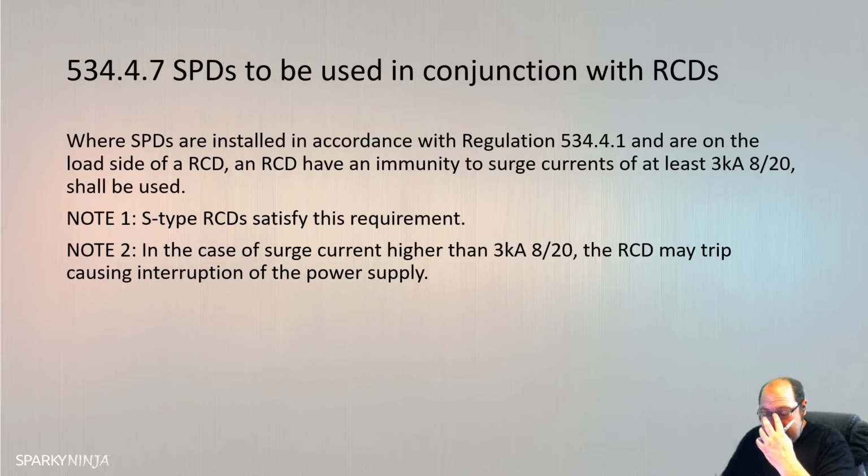You have different connection types illustrated here. I strongly suggest you observe the manufacturer's requirements with connection types anyway, but it does illustrate different connection types with regards to the configuration that is required. CT1 and CT2. Basically, a 4 plus 0 configuration or 3 plus 1. Depending on the positioning of an RCD would also determine your connection type as well.